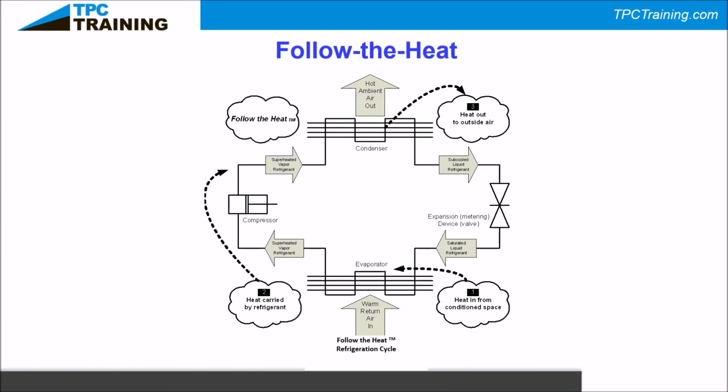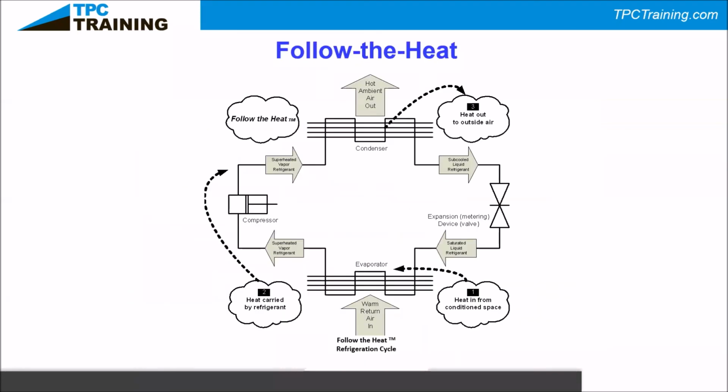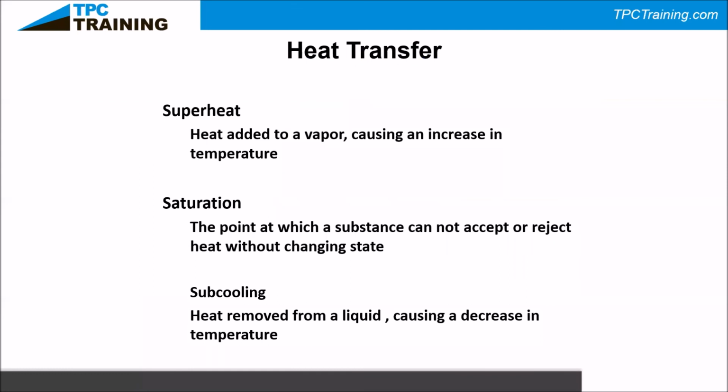Yeah, definitely. Got a great question from one of our attendees here. What's a better way to check the charge? Using gauges or using subcooling and superheat? And kind of to piggyback off that, should an HVAC guy use gauges every time he or she checks the unit? To tell you, the best option is to try and diagnose everything you can without hooking up gauges.